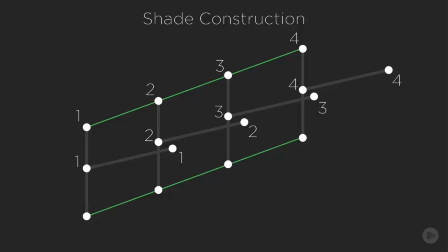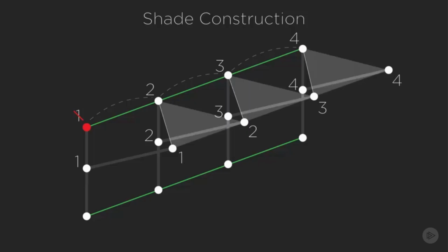By this I mean, if you triangulate the connections from one mast to the other boom arm, a list will have to be shifted and reduced in order to connect only 10 of the 11 generated points between the arms. And finally, we'll finish our Dynamo development by mapping a surface between the points that we've developed in our skeleton.